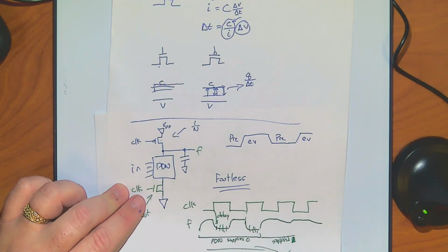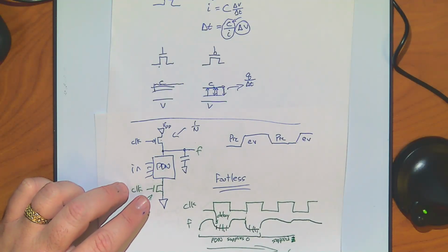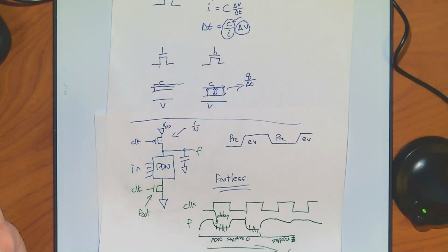That's how you make domino logic. And then they can cascade one to the next as long as you want to go. They keep getting recharged back up. It's a very strong signal. It's stupidly fast. The inverter is only 1 P gate added in, right? So it's not a significant slowdown on us, but it avoids the one problem case. And that's usually pretty much the best compromise, which is why everybody does that.